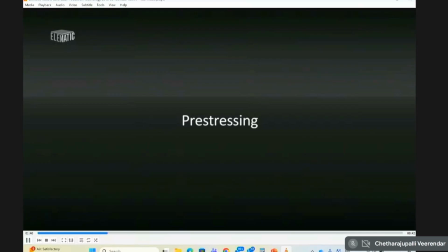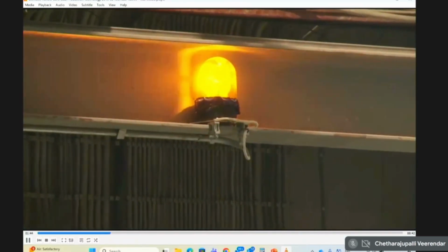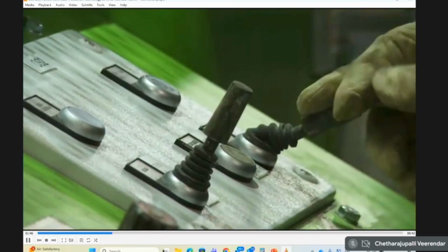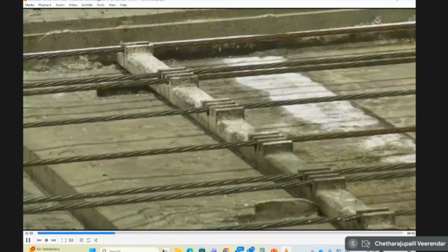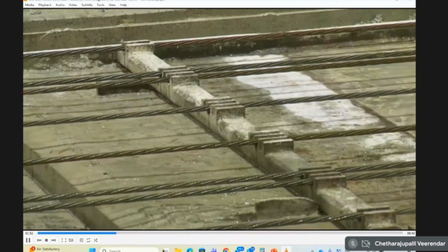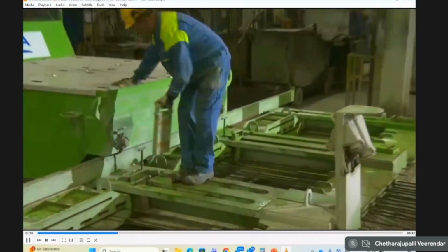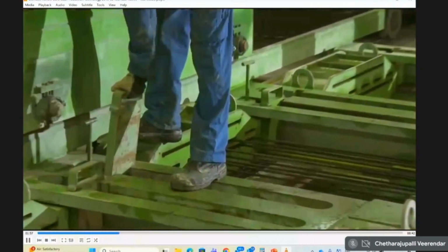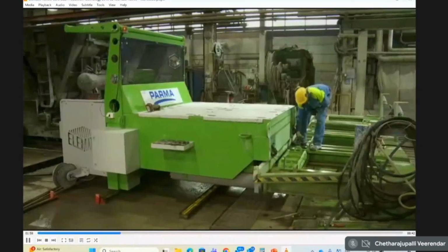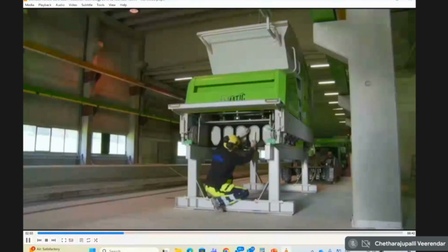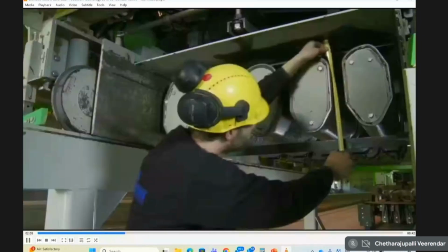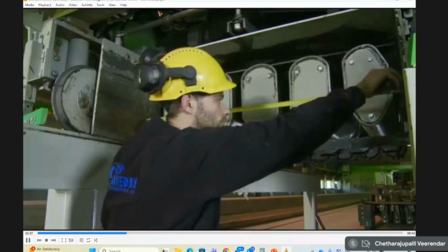And now we are going to pull the entire beam so that all the strands are stressed in a single time. We also have machines for single stressing as well, but this is a multi-stressing machine. So you can see all the strands are being stretched. About 15 centimeters of stretching goes on. You're talking about 300 tons of pressure being applied here on the strands. Why pre-stressing? To transfer the stressing force into the concrete so that it becomes better in tension.